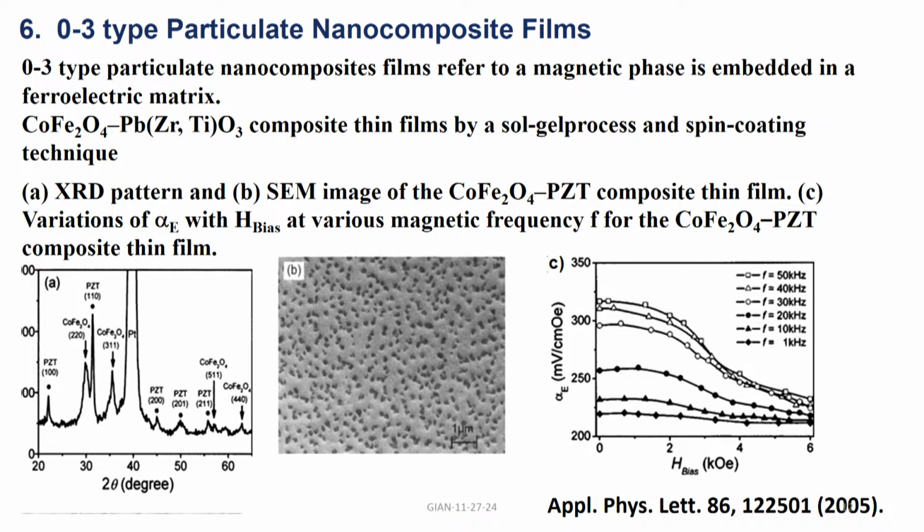There is a detector that scans the angle of reflection, and then it will record the intensity of the X radiation as a function of this angle. Depending on the lattice structure, the X-rays are diffracted into forming a series of peaks. So, you can identify the phase of the material from the position of these angles.